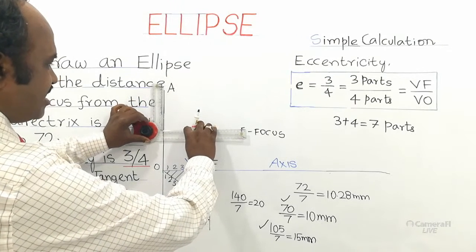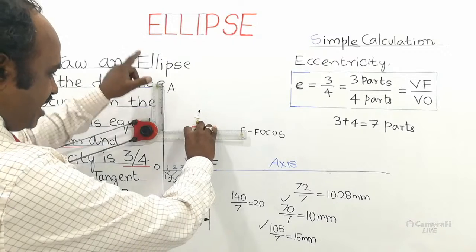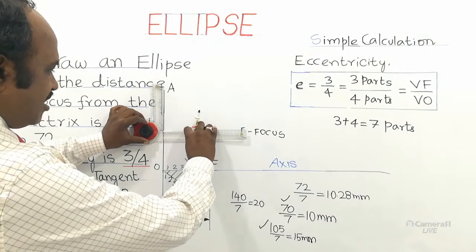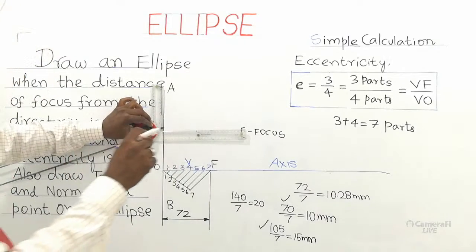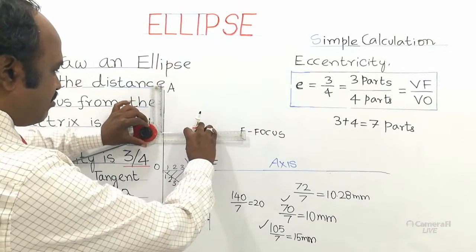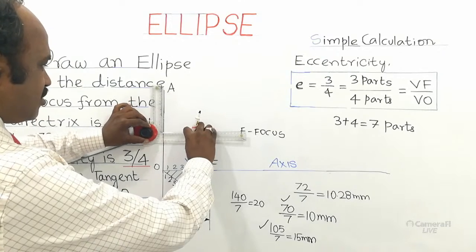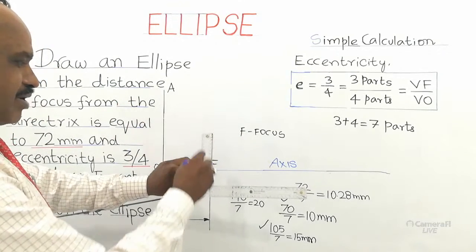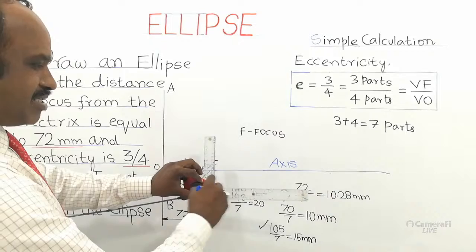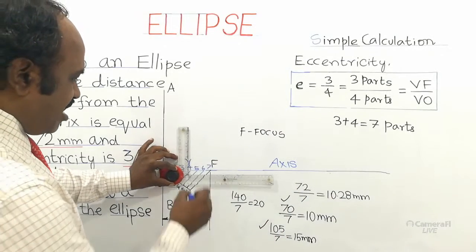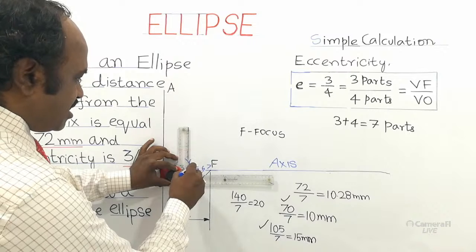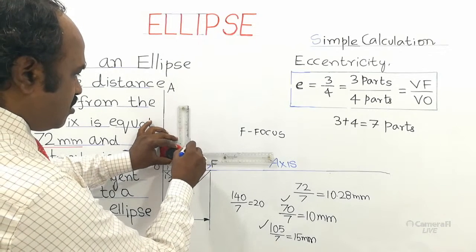The first drawn line is the directrix; place the scale vertically along it, coincide, and rotate the nut clockwise. Don't hold and turn it forcibly, the scale will break. Whenever you release and reset, loosen the nut, rotating anti-clockwise so the scale is released. Then place the vertical scale on the directrix line and rotate the nut clockwise. Don't over tighten, just normal tightness is sufficient. So the scale sits vertically, and horizontal will be 0 degree. Through point V, draw one vertical line using your H pencil.